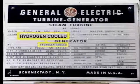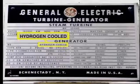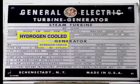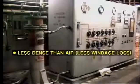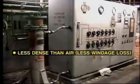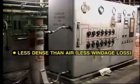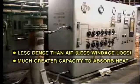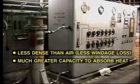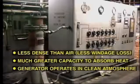When the unit size increases above, say, 100 megawatts, hydrogen cooling is normally employed. There are several advantages to using hydrogen as a cooling medium instead of air. Hydrogen is less dense than air, and consequently the windage loss, that is, friction loss due to rotation of the rotor, is considerably reduced. Hydrogen has a much greater capacity to absorb heat than air. Therefore, it is a better cooling medium. The generator operates in a very clean atmosphere.